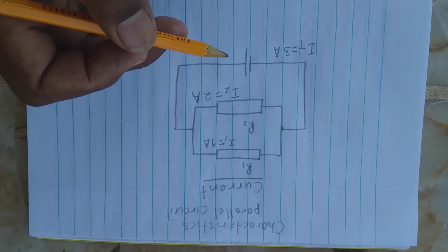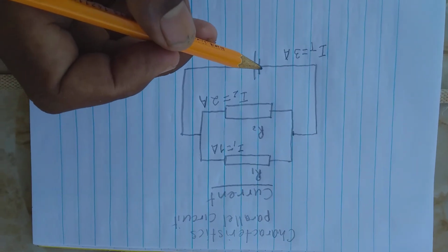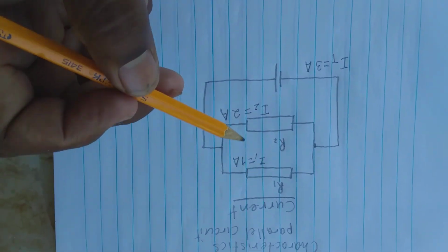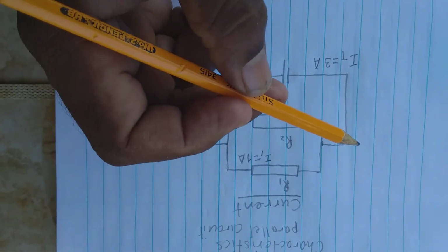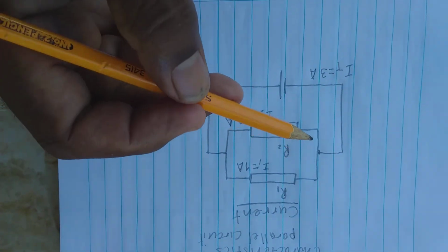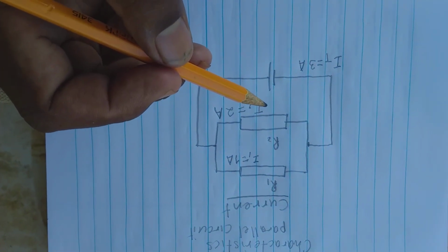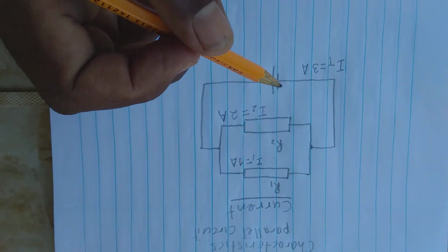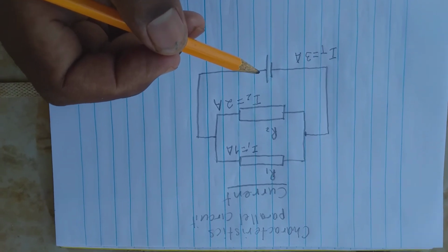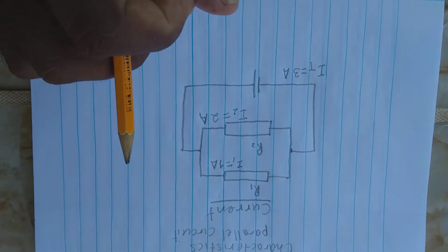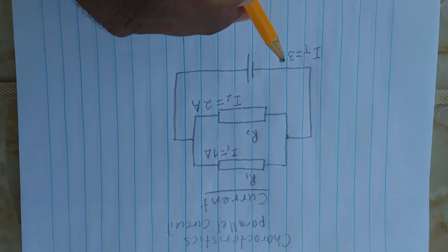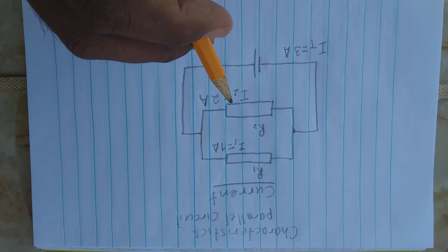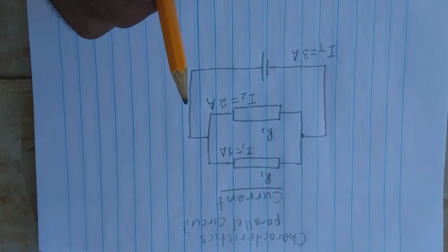So this is a characteristic of a parallel circuit. The current in a parallel circuit divides among the resistors in the circuit. We have 2 resistors here. If we had 3, the current would have divided among the 3 resistors. If we had 4, it would have divided among the 4 resistors. If we have 5, 6, 7 resistors, the current will also divide among those 7 resistors. So for any number of resistors you want in the circuit, whatever the total is, it would be divided among all of those resistors within the circuit. So again, another characteristic of a parallel circuit.